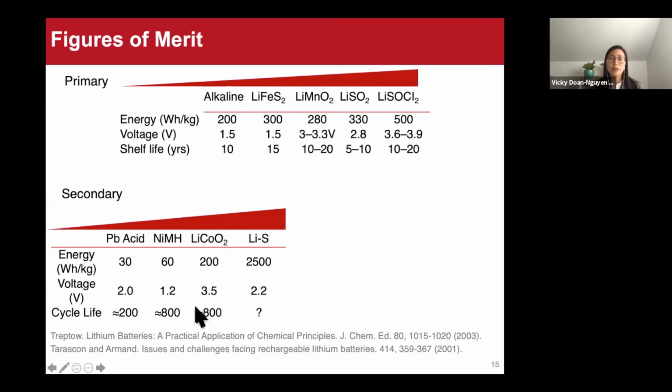We'll be focusing on intercalation base type materials where we insert lithium ions and de-insert them and not just convert the cathode material. You can see here that the voltage is quite high, 3.5 volts versus lithium. In that the cycle life, you can cycle about 800 times before dramatic capacity fade occurs.